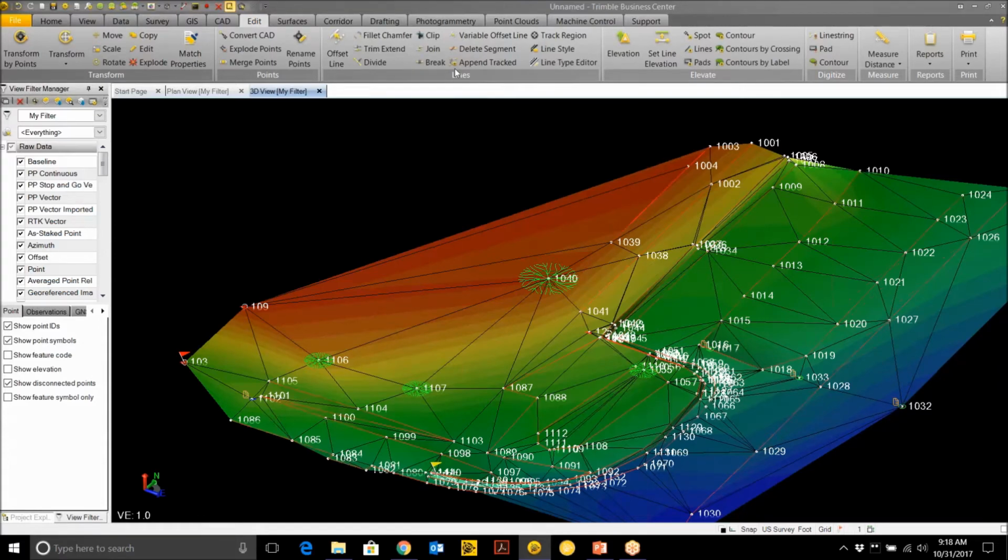Okay, so when you process your feature codes, will that note automatically appear, or would you have to manually type that note in? Right here, if you had it connected with the feature codes, so if that was a code that was already in there with the attributes, they would all come up and you'd have to hide those. So as long as you had, say it was a tree 8-inch and you wanted it to be a cherry and you wanted the attribute cherry to be shown with it, then that would come up in your attribute file.